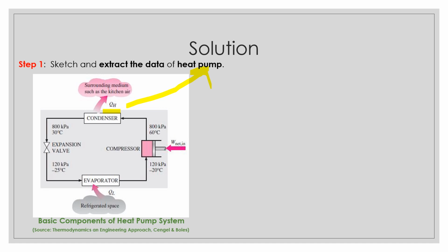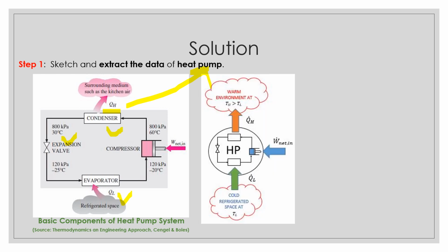The compressor, as we know, increases the pressure and temperature, the condenser removes the heat, the expansion valve is a pressure dropper, as well as reducing the temperature, and the evaporator receives the heat. We can simplify this diagram by having this one.